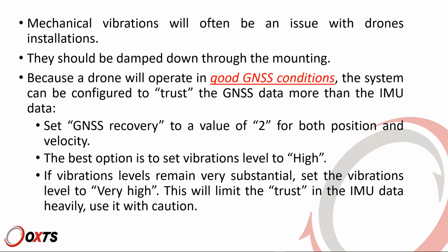The system will trust your judgment, and if you are telling it that the IMU data is really bad, this is what very high vibrations would mean, because the noise will be so large that it would be difficult to distinguish between a real acceleration and the vibration. It can still extract sensible data. Obviously, it won't be as accurate as having everything set properly, or set to, for example, high vibrations. So you can do this, but use it with caution.